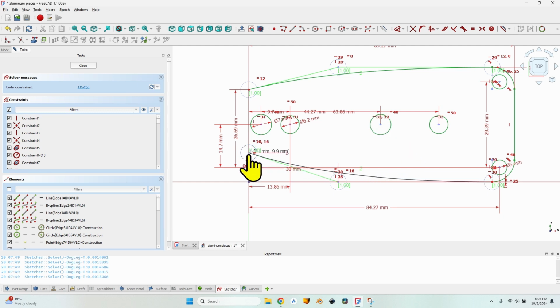I can see that this point is able to move up and down, but I know that this series of holes is in the center of the object. So let's create a new point. I create it somewhere else so I can easily select it. First, set it to construction geometry, press on this button, and now let's place this point on this line. Press O for point on object, and now select the top corner, the bottom corner, and our newly created point.